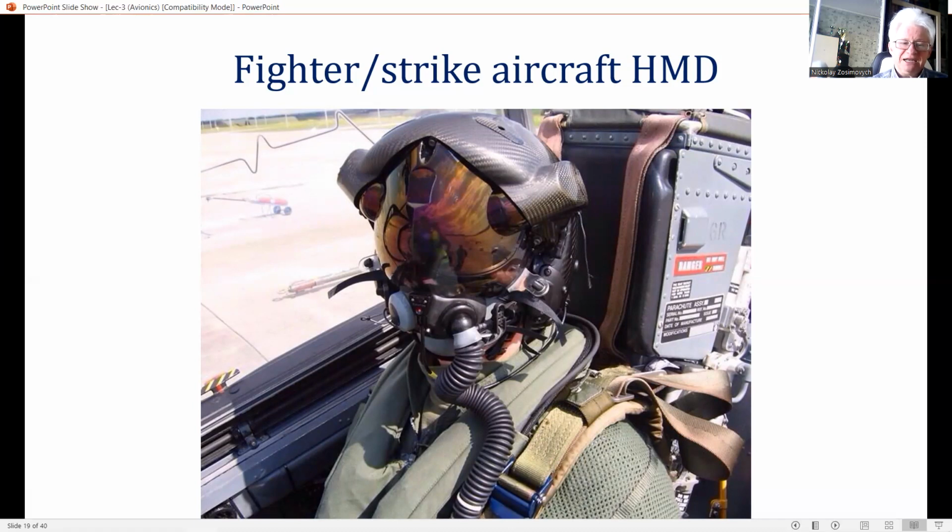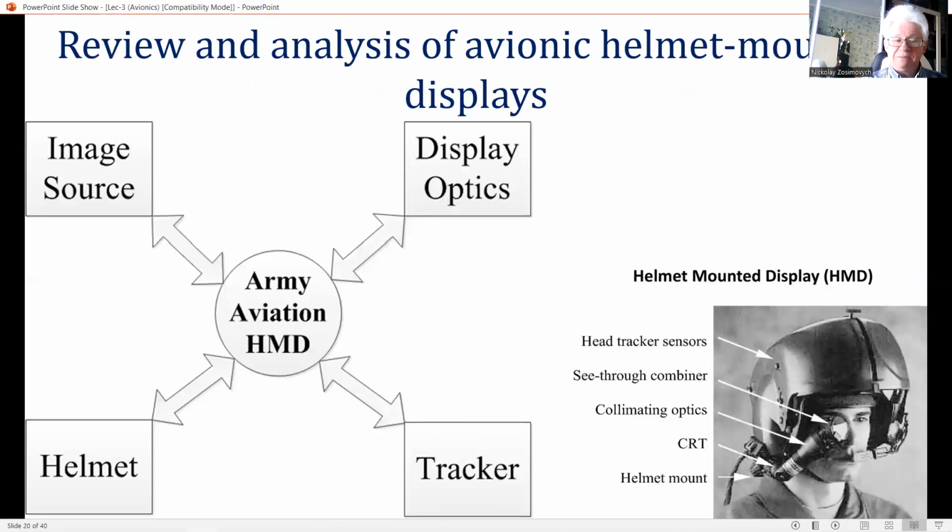More than 70% can be achieved with no coloration, and display accuracy is also insensitive to visor rotation because of the spherical shape, and partial raising of the visor is possible. For example, to carry out the Valsalva procedure, which means pinching the nostrils and blowing to equalize the pressure in the ear. The combiner and collimation function is thus achieved without adding additional weight to the optical system, as the visor is essential anyway.